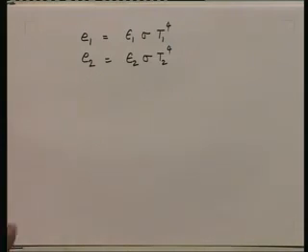And as I said a moment ago, I am going to analyze what happens to the radiation which is emitted by one surface. What is going to happen is, any radiation emitted by say the surface 1 or the surface 2 will go to the other surface, get partly absorbed and partly reflected, will come back to the original surface where it will get partly absorbed, partly reflected, will again go back to the next surface, partly absorbed, partly reflected.